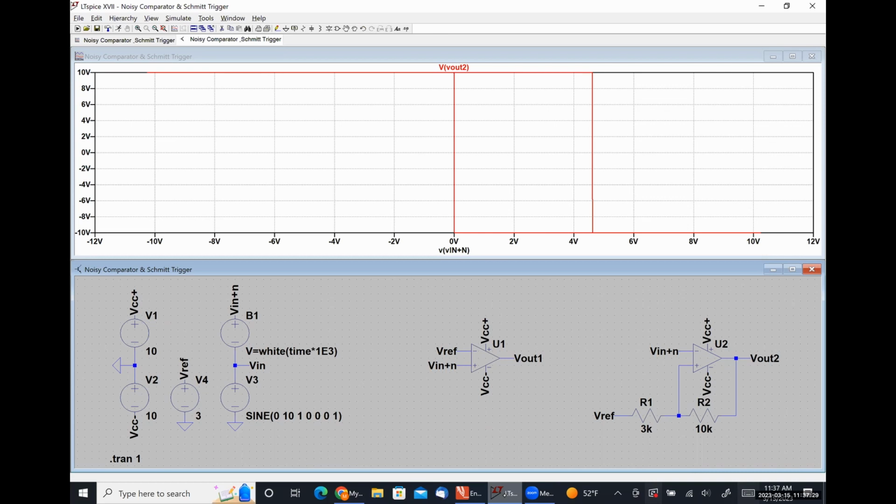Yes, Gabriel. Do we need a white noise to create it? No, not at all. The noise is completely and utterly irrelevant. I'm just continuing to add the noise in because I want to show you guys that it doesn't matter whether or not the noise is there. This thing behaves in this particular way, right? The noise is what's messing up the performance of the comparator. And we are fixing that error in performance by applying positive feedback.